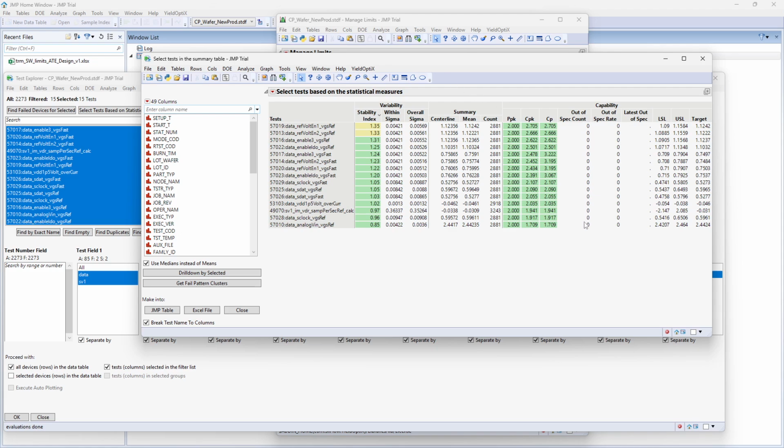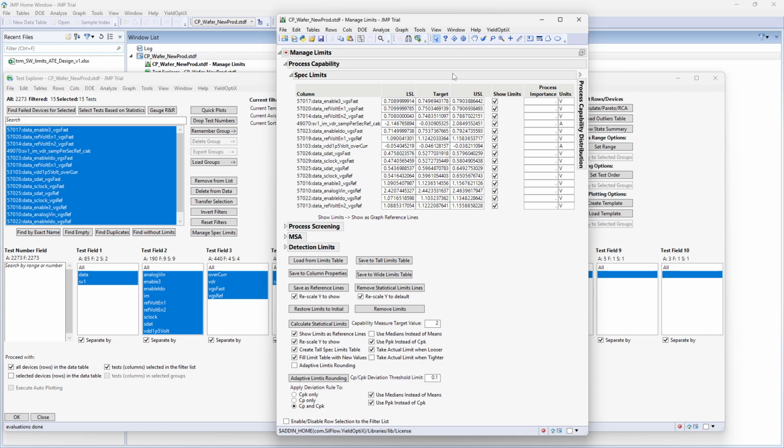Out-of-spec values drop to 0, and the limits are updated with a consistent PPK value of 2, including cases where one of the original, more relaxed limits was retained. In all cases, the calculated limits tend to be difficult to read, compare, or interpret, as they are generated with maximum numerical precision to meet the exact target capability measure.